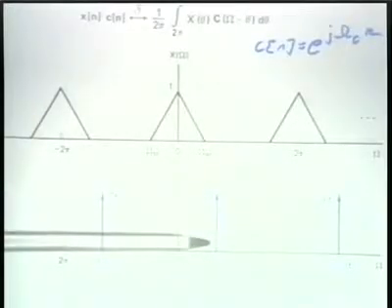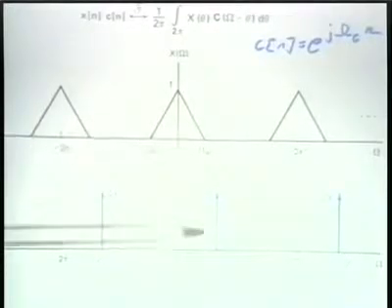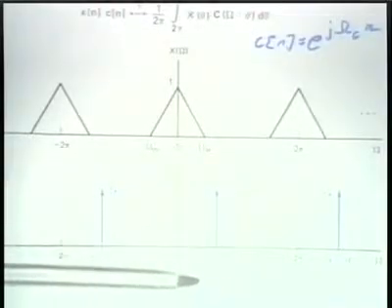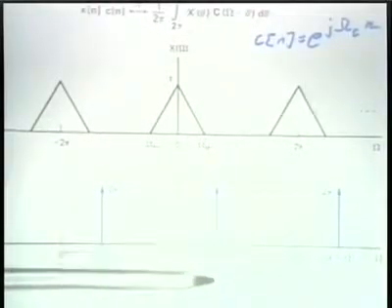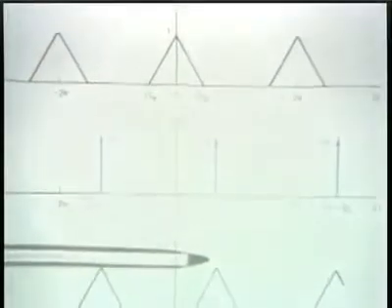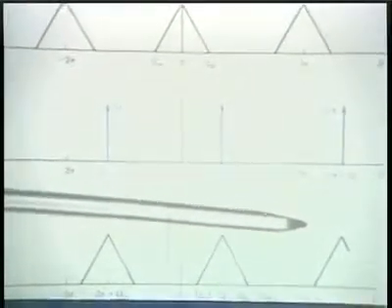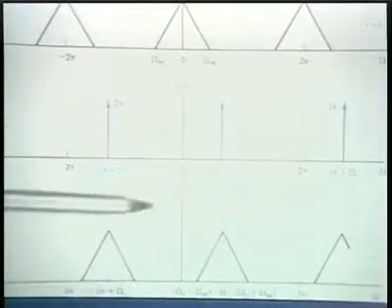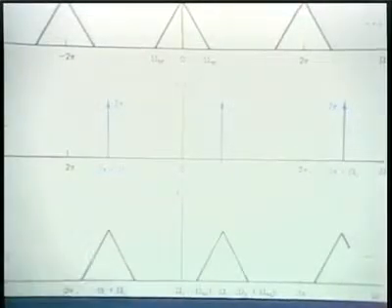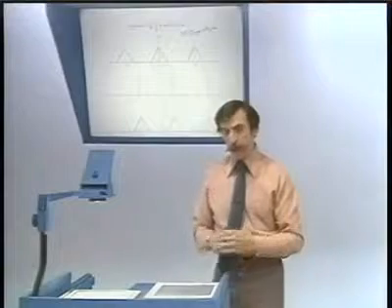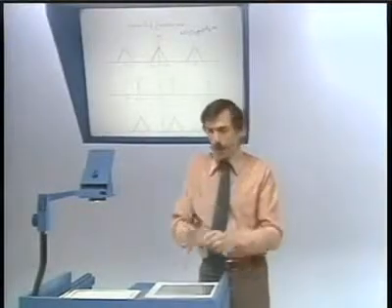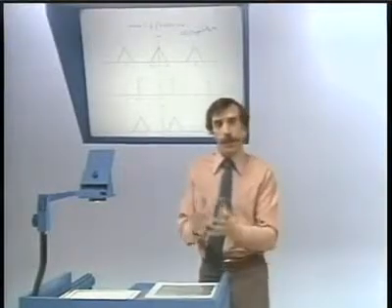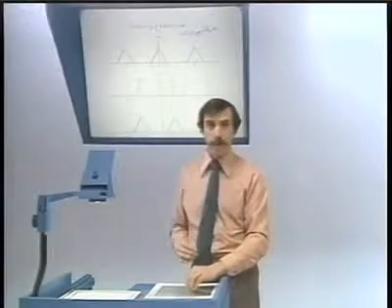And the result is then this spectrum shifted to a center frequency, which is the carrier frequency omega sub c. So the result of modulation with a complex exponential is a straightforward shift of the spectrum so that what occurred around 0 frequency now occurs around the frequency omega sub c.